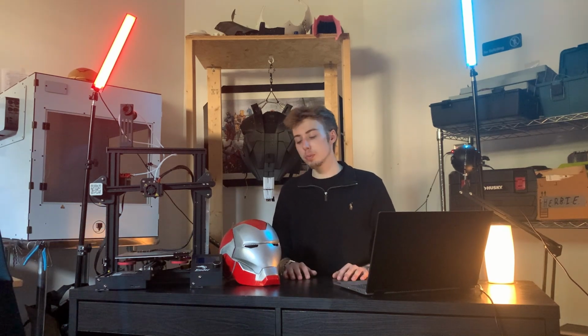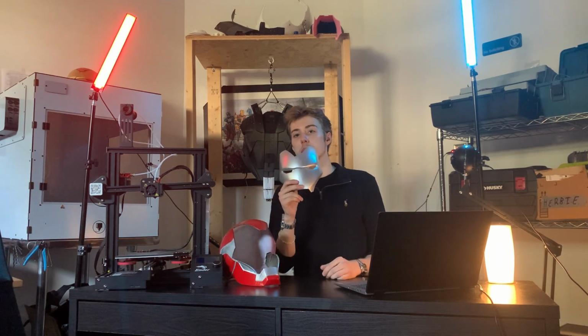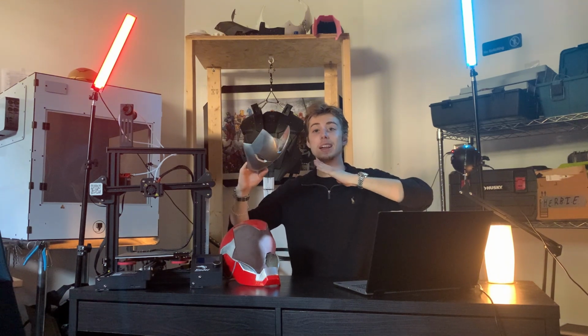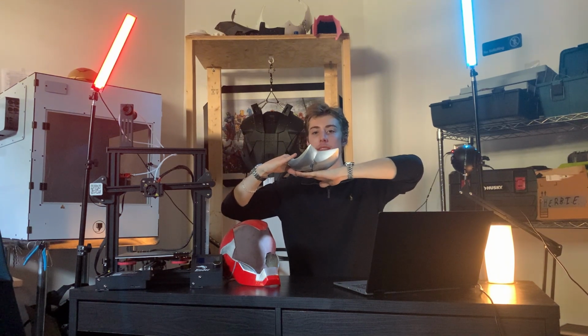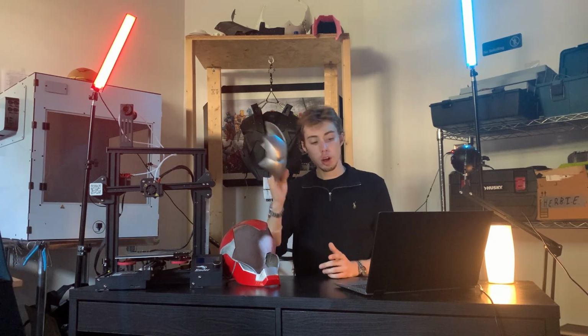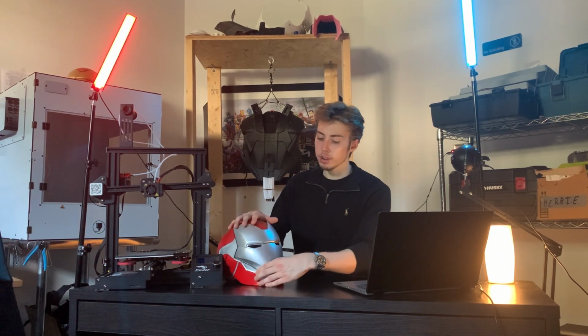So for example, if you're 3D printing something like an Iron Man helmet and you're at the faceplate part, well, you want the faceplate to be the prettiest part of the print, right? So assuming my hand is the bed, I wouldn't 3D print it like this, because then you're just gonna have supports all around here that make the front of it look ugly, right? So it all depends on what you want to 3D print and how you're gonna 3D print it. But for this headphone stand, it's not really here to look super nice, and the supports won't really be too noticeable. So again, just keep that in mind with what you're 3D printing.